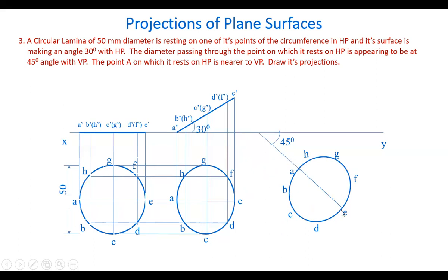This AE is taken on this line, and by taking these 2 points as reference, we have marked all the other points, joined them by a smooth freehand curve. Now this top view and this top view both are the same. Absolutely, they both are the same. There is no difference at all. Only thing is we have redrawn the same top view here in a different position. That's all. Okay. AE is here parallel to the reference line. But now here it is taken at 45 degrees angle to VP. That is the only difference. Otherwise, the same top view is reproduced.